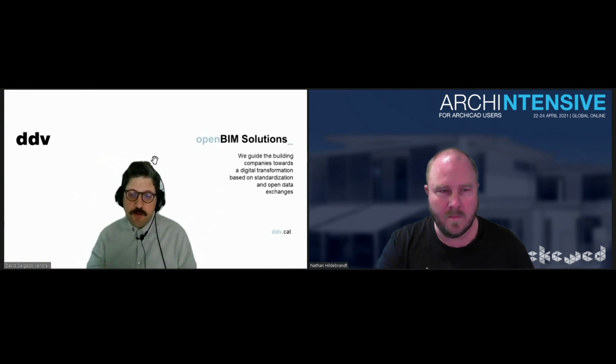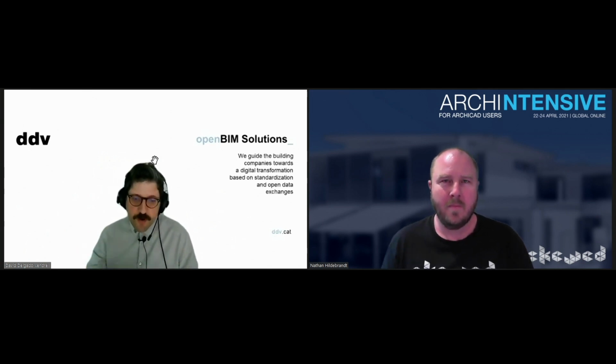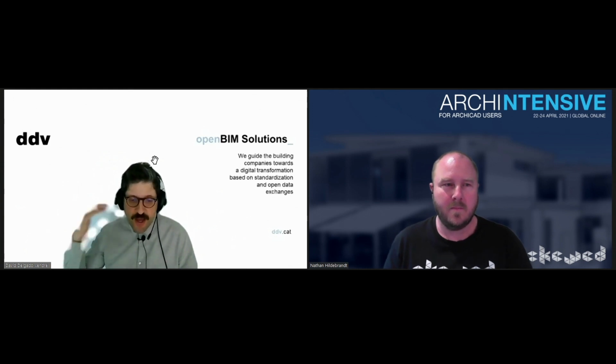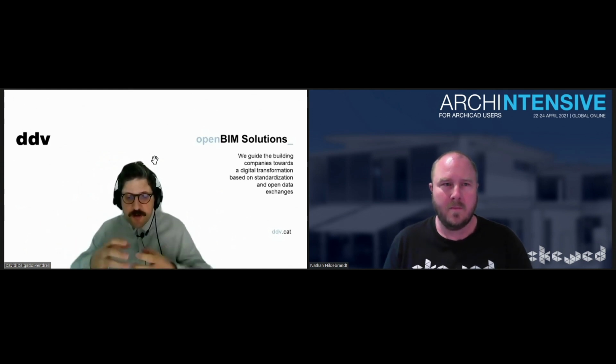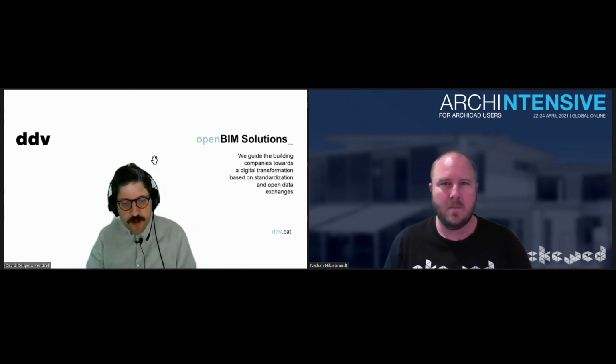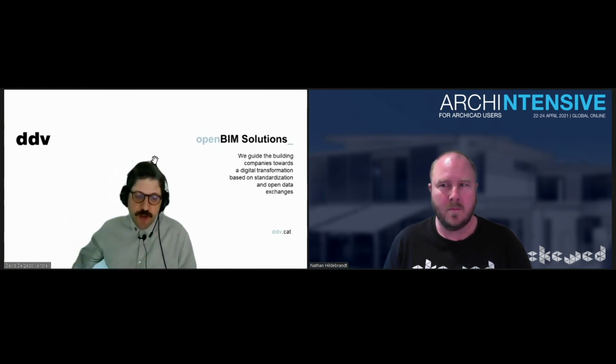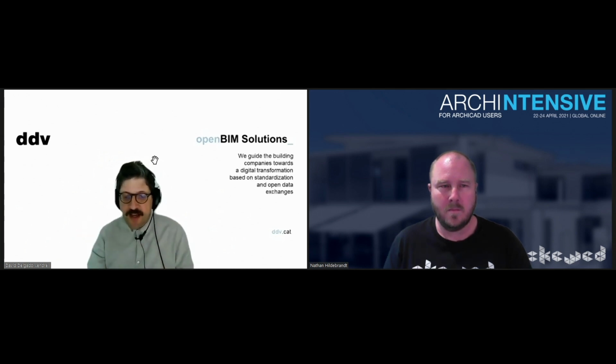So once we are working with color point clouds, in some cases, not all of them, of course, because there are also shadows and so on, because of the type of work on site, you can skip the use of 360 images because the point cloud itself is providing you meaningful information to enable you to model.